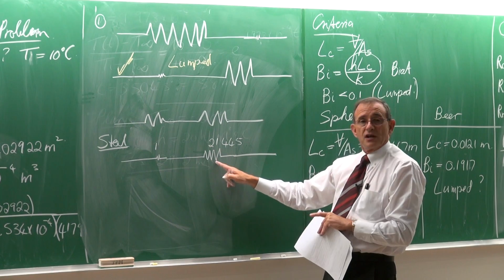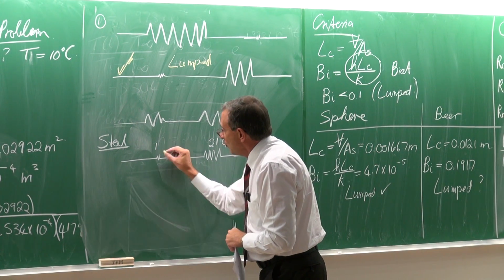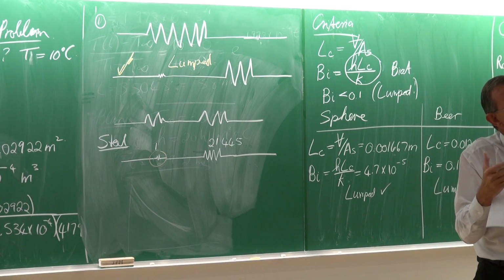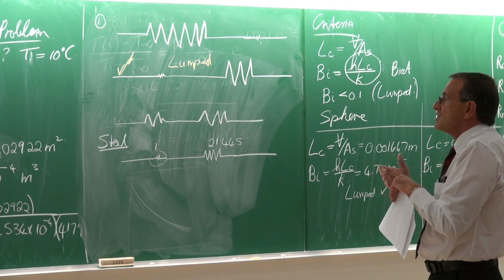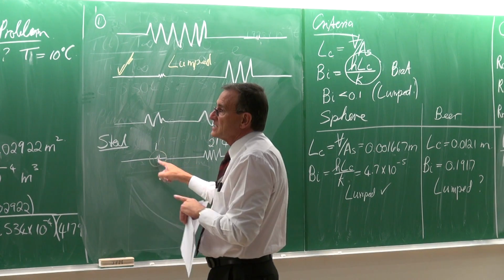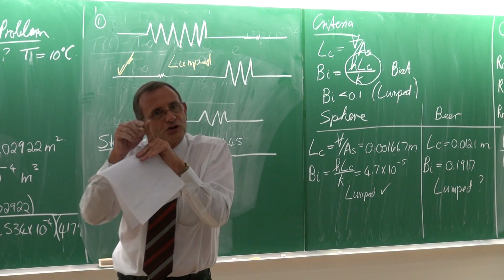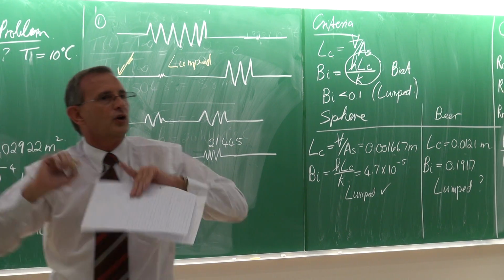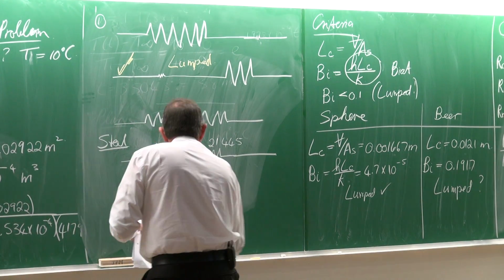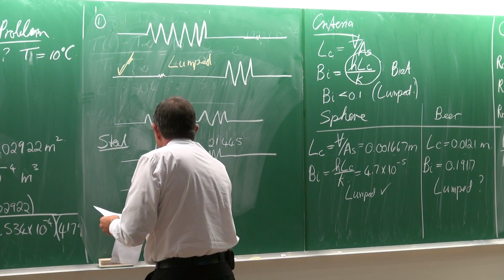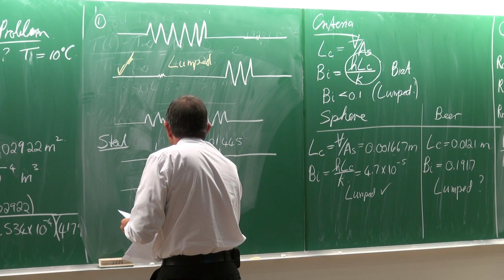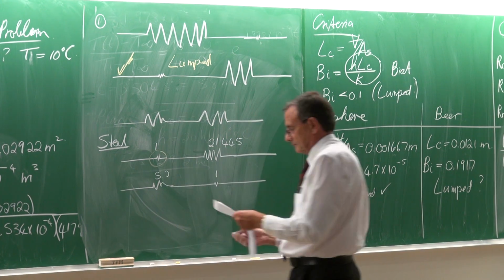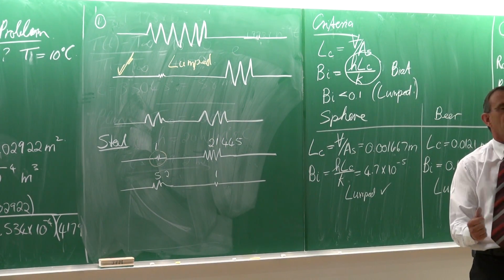So the flow of heat through here, there's no resistance through it. And that is the reason why the lumped system approach works very well. It also says that in that body, there's almost not going to be any temperature differences. They're all going to be approximately the same. In the case of the beer, it works out as 5.2 on the inside, and that one there is 1. Okay, 5 to 1.